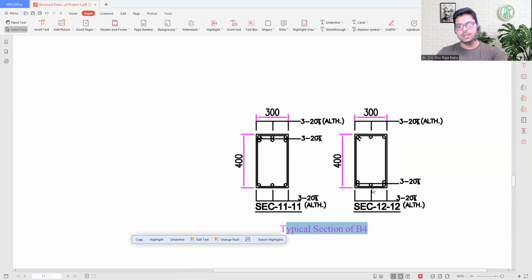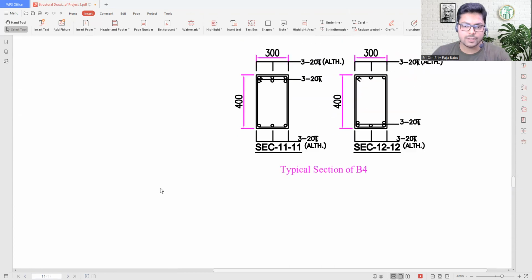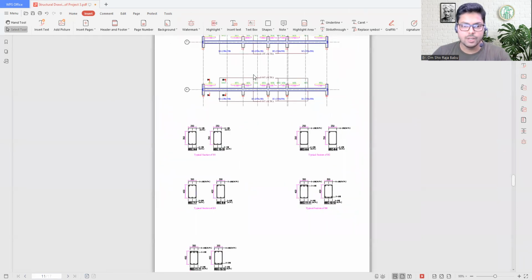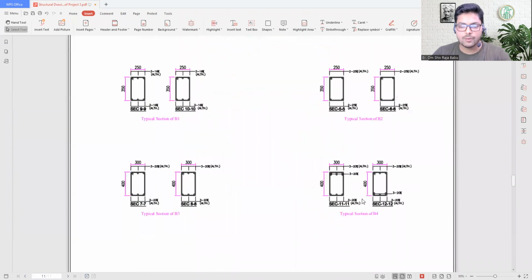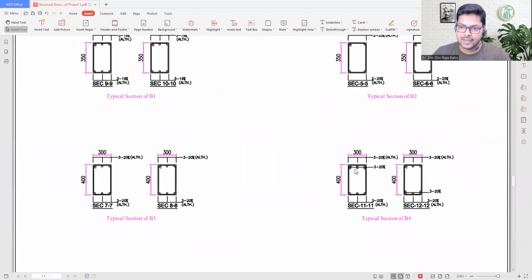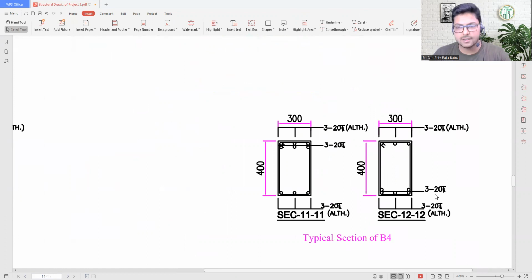This is going to help you a lot while you are making the drawing, or while you are working on site. If you find a drawing with a marking of HT1 and HT2, then you will exactly know how much of the portion we have to provide these bars at the end, that means on the top, and where we have to provide the bars at the bottom, and consider that as a central region. So HT1 and HT2 markings are very much important on site.